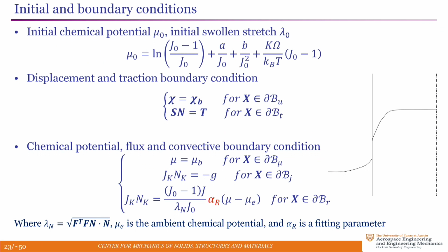There is an interesting thing that happens in the boundary condition for moisture flux. If you think the chemical potential in the interior of the specimen is constant, chemical potential is going to have a gradient as it approaches the free surface. It cannot be a step function jump across that. And the chemical potential on the outside, let's say, is at some uniform value. The exchange between these two, you can use a Dirichlet boundary condition which says that the chemical potential here must be equal to the chemical potential.